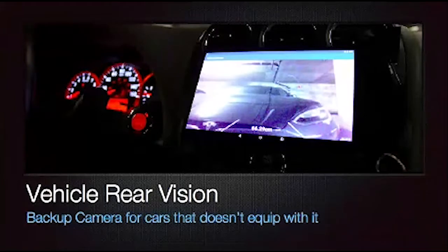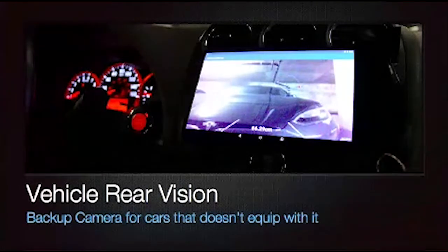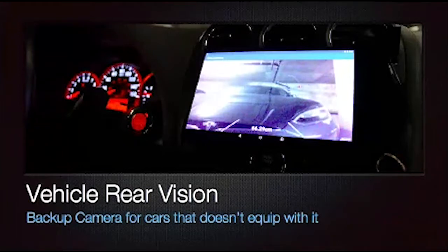So why do these cameras run only on USB 3.0? The RealSense camera only runs on USB 3.0 because it contains multiple cameras: two visual cameras and one infrared, along with all the logic in it. The data transfer is more than what USB 2.0 can handle. So that's the reason why. It's based on the general spec.